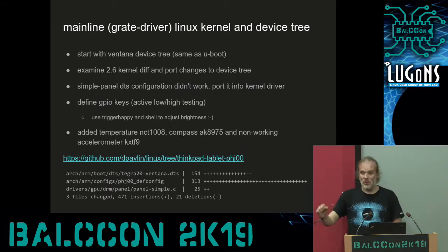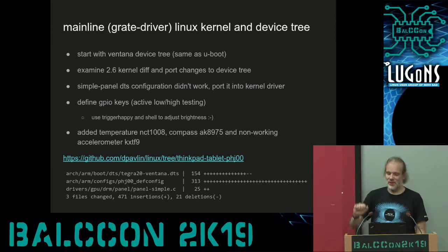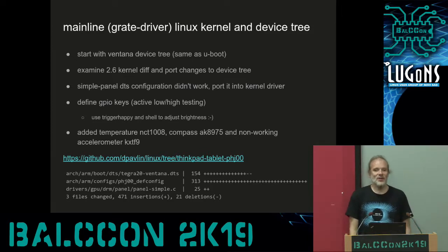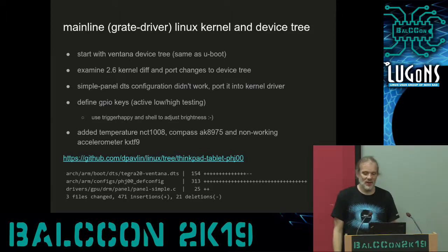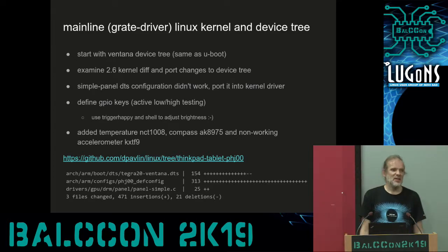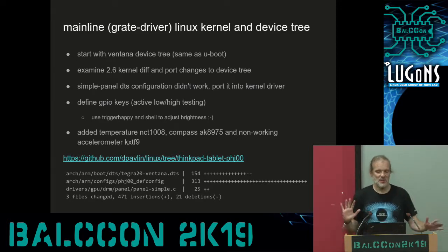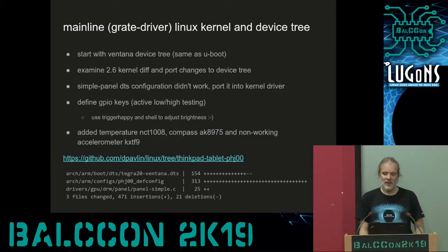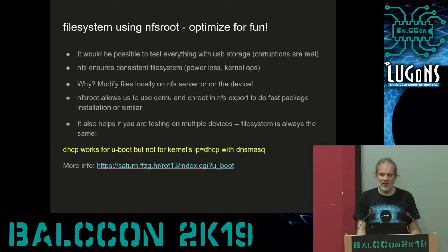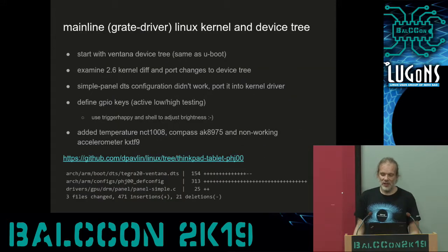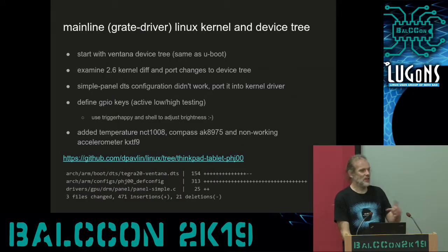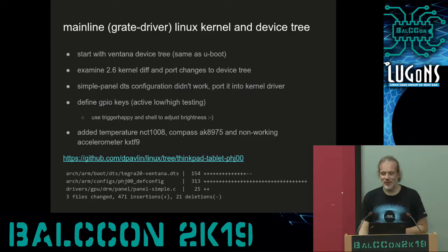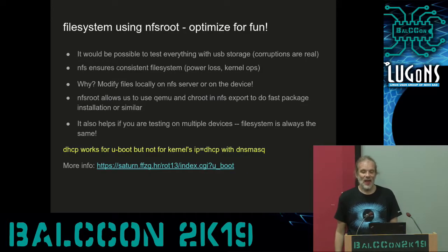Then I said, oh, this is very good. I have U-boot, now the kernel. So I got to GitHub, compiled the kernel, again, did some minor changes like defining sensors, GPIO keys, and stuff like that. And in less than 400 lines, I actually had a booting system. I thought that the next slide, this is the picture of the booting system, but it will come later.